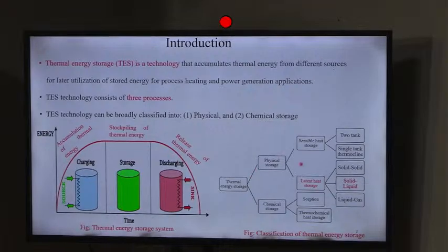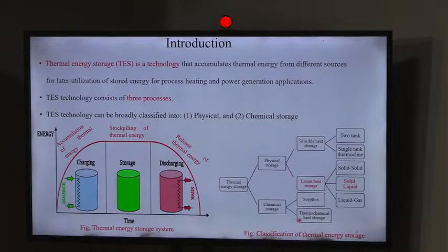But thermal energy storage, in terms of sensible as well as latent, has been used for a long time. As I was telling, if you are having say a bag of sand and you are exposing it to sun, the sand bag, because of its heat storage capacity, will keep the heat. And that heat, if you want to pump it out, just put a pipe through it and a water circuit. That water will get heated and you can use the energy which is there in that bag of sand. So that is a very matured way of harnessing low grade or thermal energy when we are comparing it in terms of the storage.